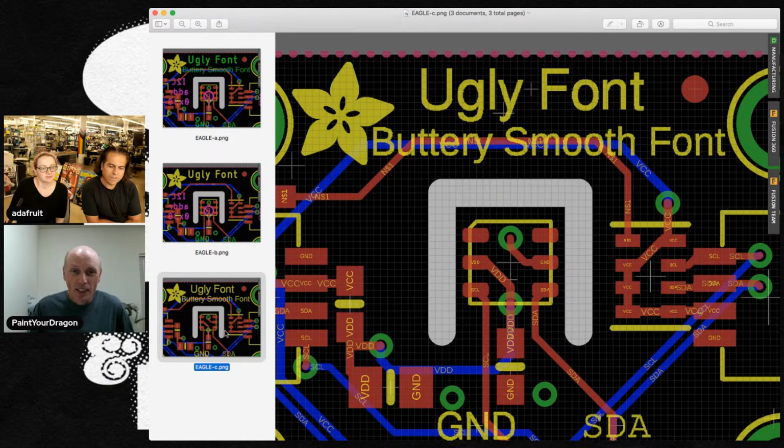This is really helpful. And someone asked in the chat, can you add fonts to Eagle? Phil, why don't you just add the font to Eagle? Because you can't. There's the ugly vector fonts and the smooth font that you can't use in silk. There's only the one vector font. Well, there's 2 versions of the vector font. One is just skinnier than the other, and then there's the proportional font that you cannot actually use. So this actually solves the problem of how do you have custom fonts?